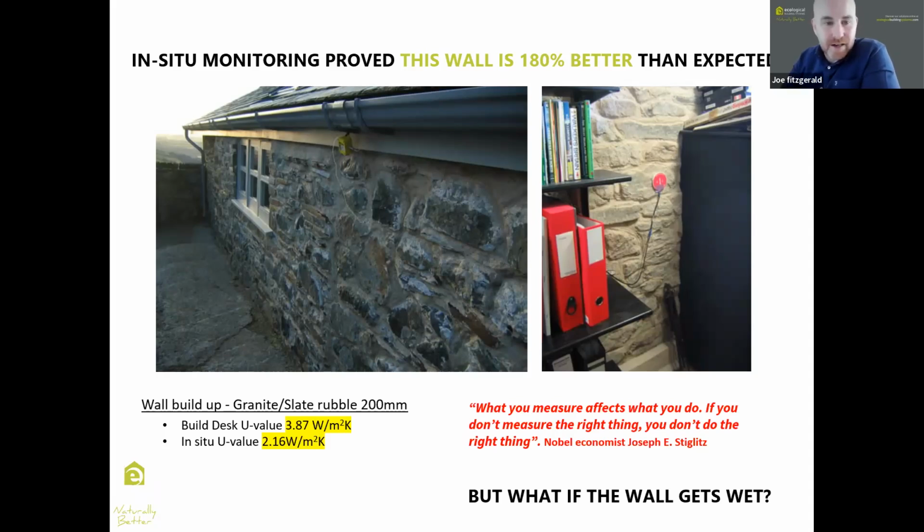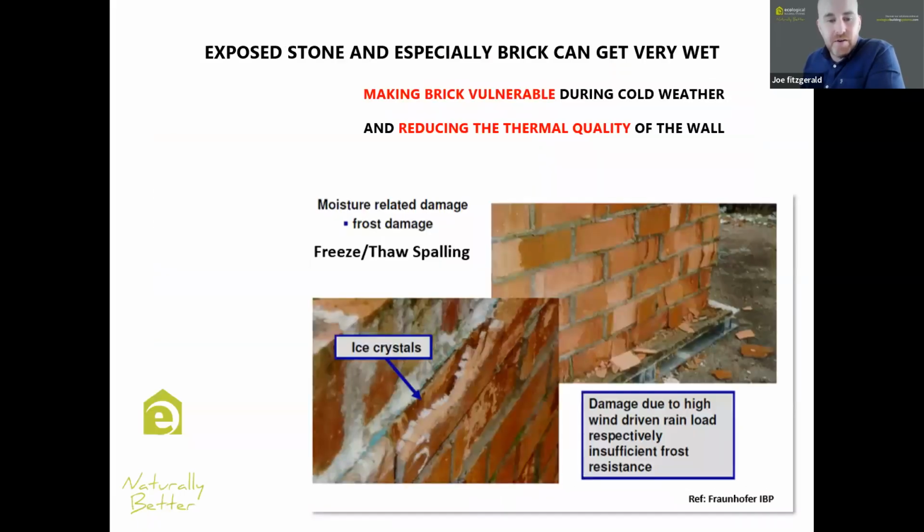Generally speaking, that starts with the pointing. If you don't have a plaster on it, it's vulnerable and it will get wet. But if it has appropriate and adequate pointing, that wetness or that dampness can drain from the stones into the mortar joints, evaporate harmlessly, and keep the building dry in an ongoing way. So it kind of stays in a cycle. But if you've poor pointing or inappropriate pointing like cement, that can really reduce the wall's ability to dry. And it can start to put vulnerable masonry like brick under duress.